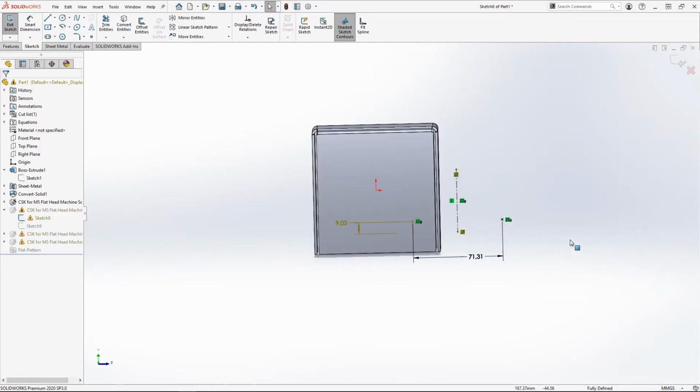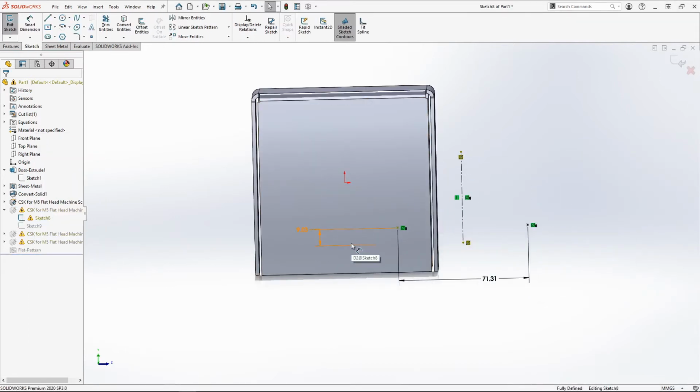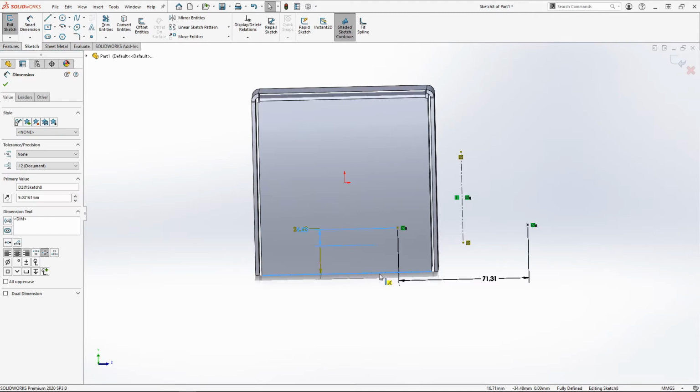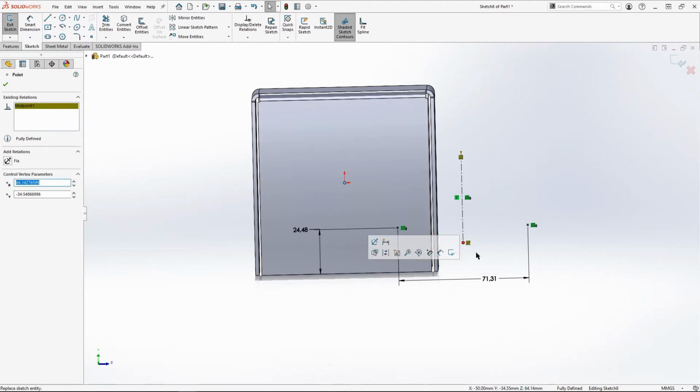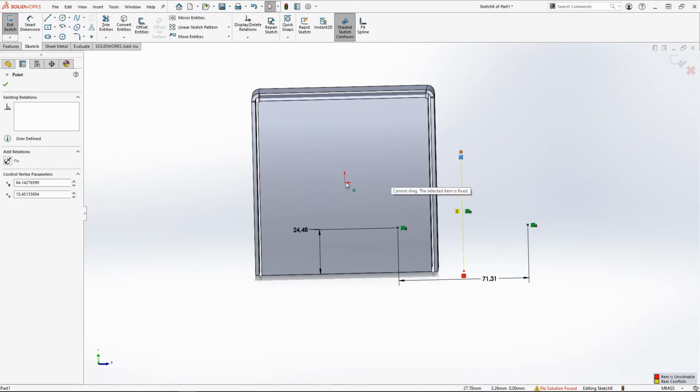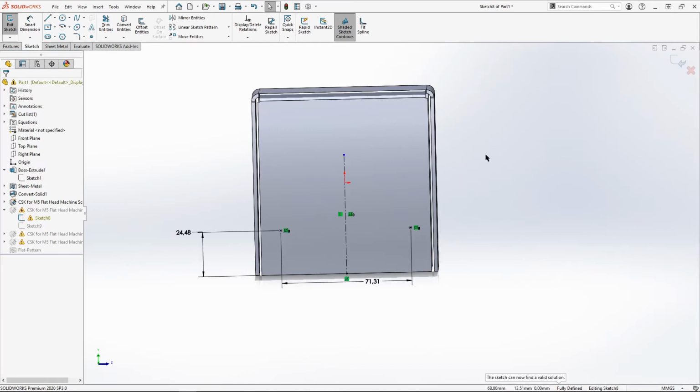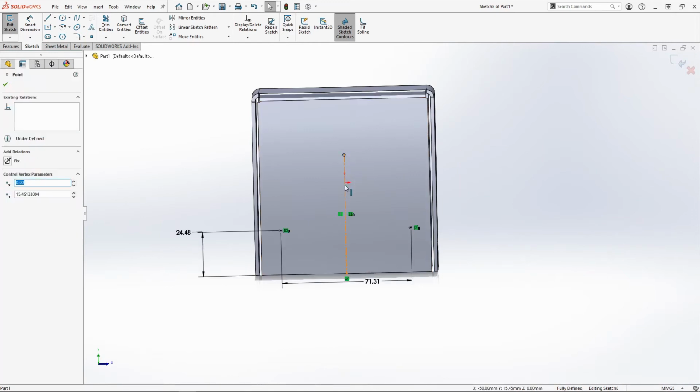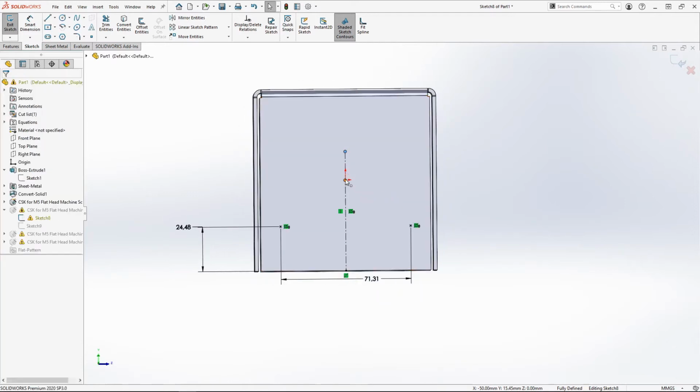I'm just going to say, edit the sketch, and you'll see there's the dangling dimension. Now this one's fairly easy, just drag it to this bottom edge here. This one I am going to, here it is, just drag that onto that edge, and this one just select. I'm just going to delete that, and make coincident with the origin.